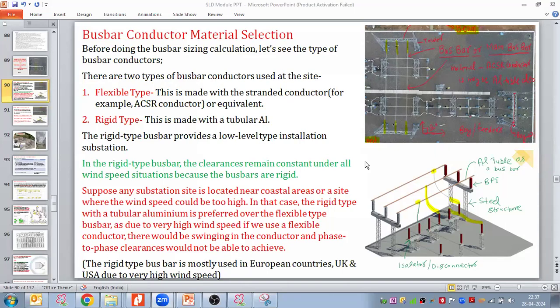Sir, generally, if you go above 66 kV, we will go for the CVT instead of VT, right? So in 400 kV, we can use the VT. Yes, we can use the VT, even in 400 kilovoltage, if you are making any renewable solar substation or renewable power plant, and you are doing the tariff metering or revenue metering, for that purpose we use the metering CVT, metering CT and metering VT, and that metering VT is a simple EMVT or IVT. So yes, we use it, but the cost would be higher. That is the only reason. There is no harm in that. We can use it.